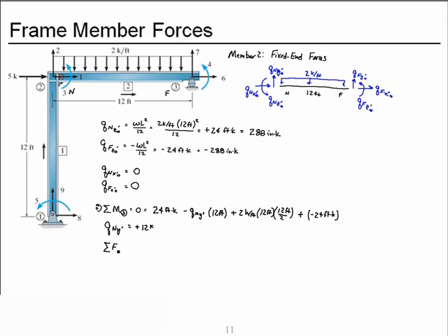Now let's sum forces in the y prime direction for this member, up being positive in this case, we have the 12 kips at the left end minus the 2 kips per linear foot acting over 12 feet plus the far y prime, oops, forgot our naughts there, y prime fixed end force. Solve that for my fixed end force and we get a positive 12 kips also.